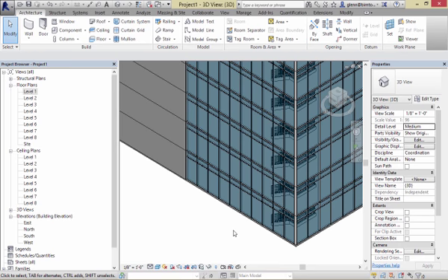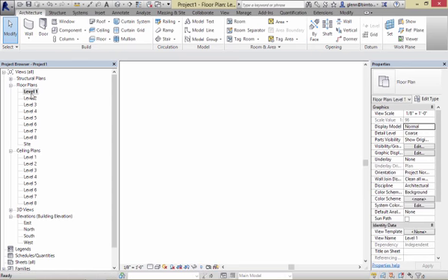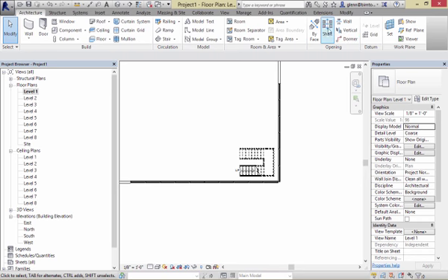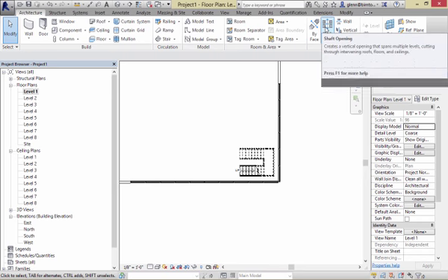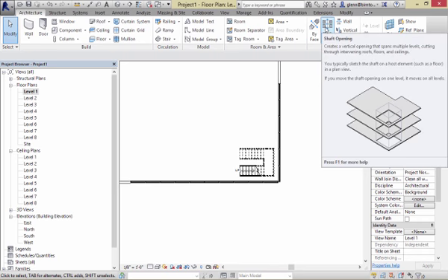So we now have this fantastic looking stair going up there. We need to cut the hole in the floor, as you know. So let's talk about how you can do that. We could go to level 2 and cut that hole, but the other way I want to recommend is, there actually is a special object called a shaft. What shafts do again is they cut through roofs, floors, and ceilings. So they do a pretty good job of kind of tidying everything up. So you only have to sketch it once, and then it'll kind of take care of subtracting that from everything.